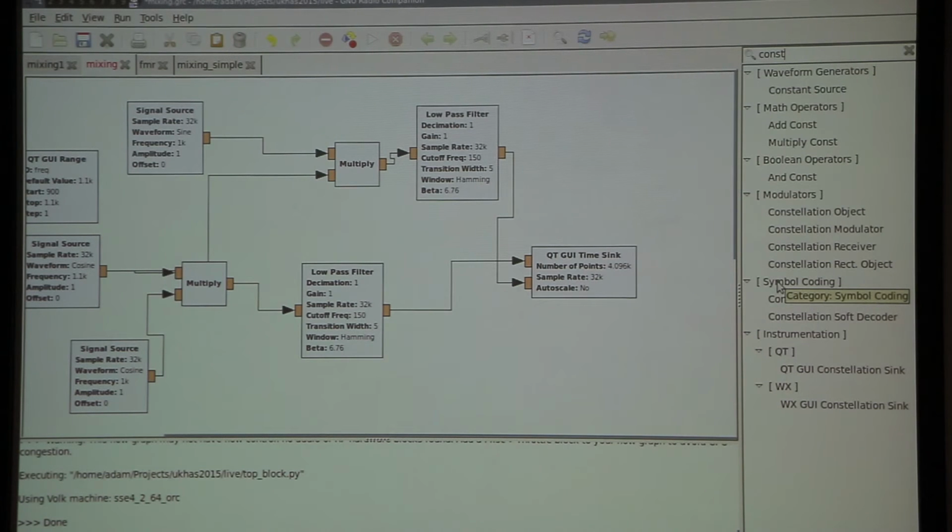Yeah. But if the signal you're listening to changes slightly, for example, if it's a HAB and it transmits by changing between two different frequencies, one represents a binary 0 and the other 1, then when it's on the 0 frequency, it's at some spinning rate. And when it shifts to the 1 frequency, it will be spinning faster on your IQ plot.